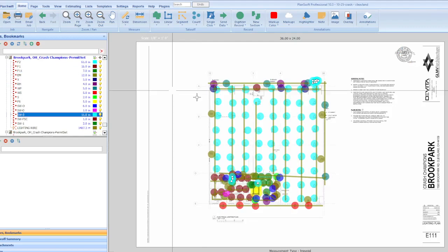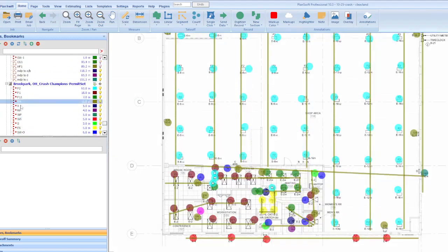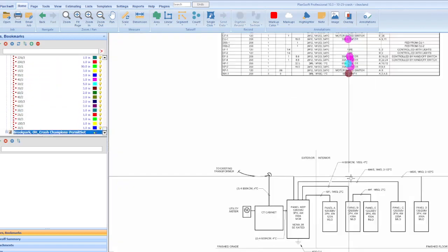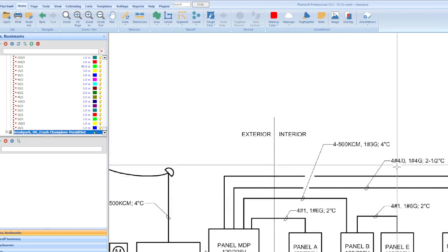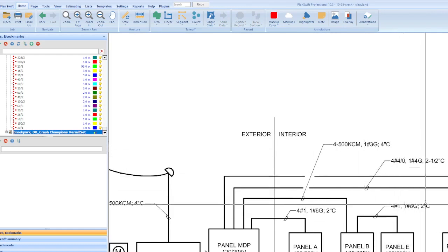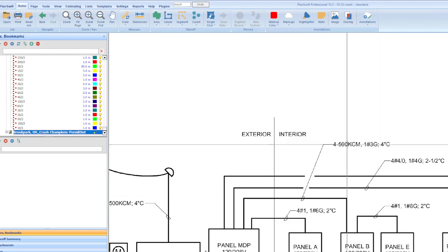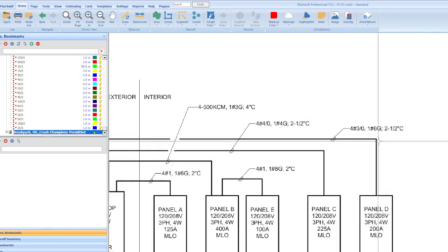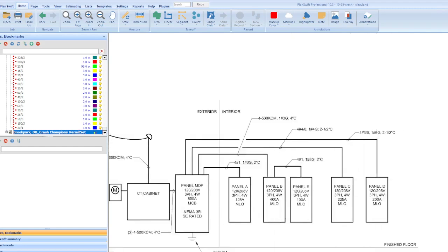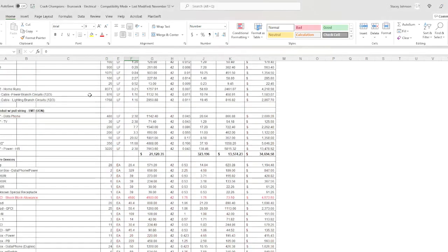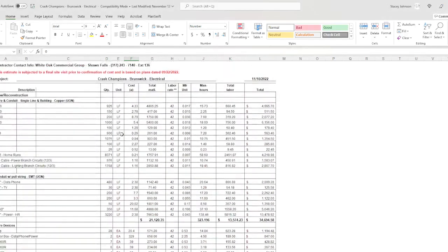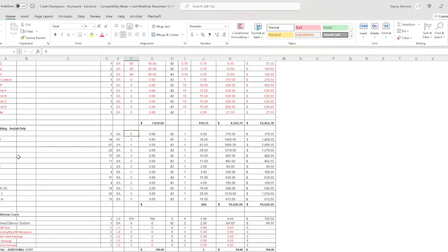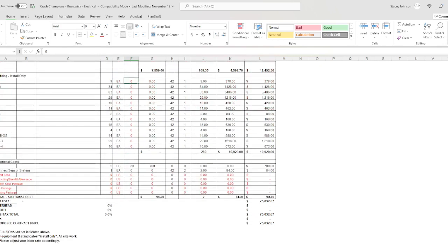Good counting tool. Count all your devices, run all your wire, and pay good attention to your single line because this is where the money is. Make sure you measure those lengths very well, because those higher-gauge wires are very expensive as opposed to number 12, so you want to be very accurate. Then you have a beautiful estimate all broken down in the way you want. The way we know our electricians like it is all the wiring and conduit, all the wiring devices, then everything in the single line and the disconnects. Then we go to the lighting plan and then any additional items.